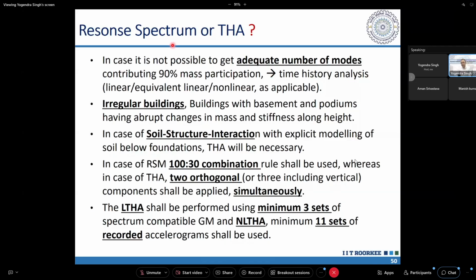So for example, if I am having a bridge with well foundation, and when I subject it to modal analysis, I will get the mass participation only corresponding to the substructure that is above the well and the superstructure.